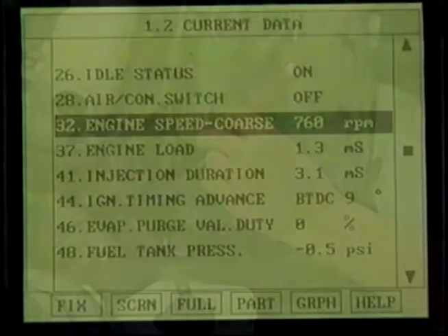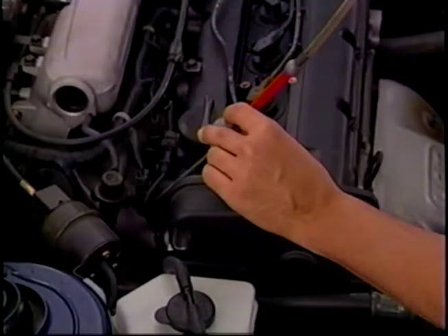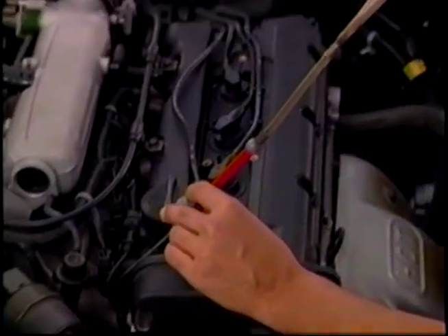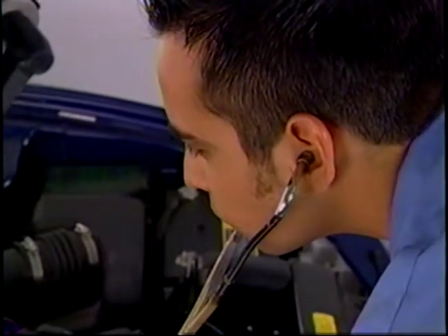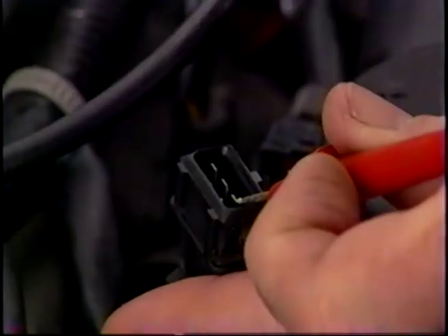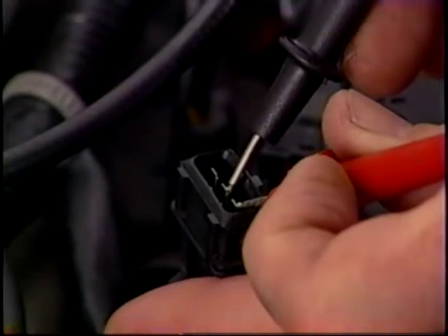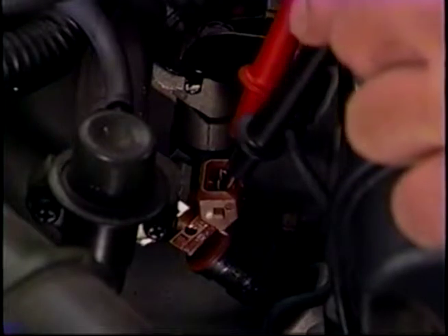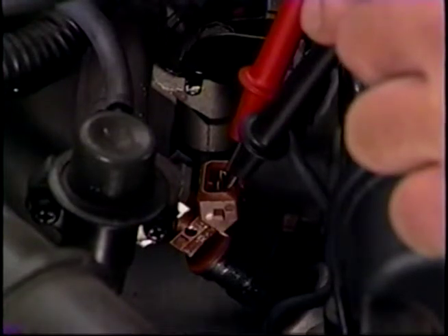If there is no drop, the injector may not be opening, or the injector may be clogged or restricted by carbon buildup. A quick test to see if the injector is working is to use a stethoscope to listen for the injector click. If it's not clicking, the coil may be open, or there may be a problem with the injector signal from the PCM or the wiring. If it is clicking, then use a digital multimeter to check for voltage at the injector. Voltage drops across the circuit can show high resistance that can cause a lower than normal voltage at the injector. An ohmmeter can be used to check the injector coil resistance.